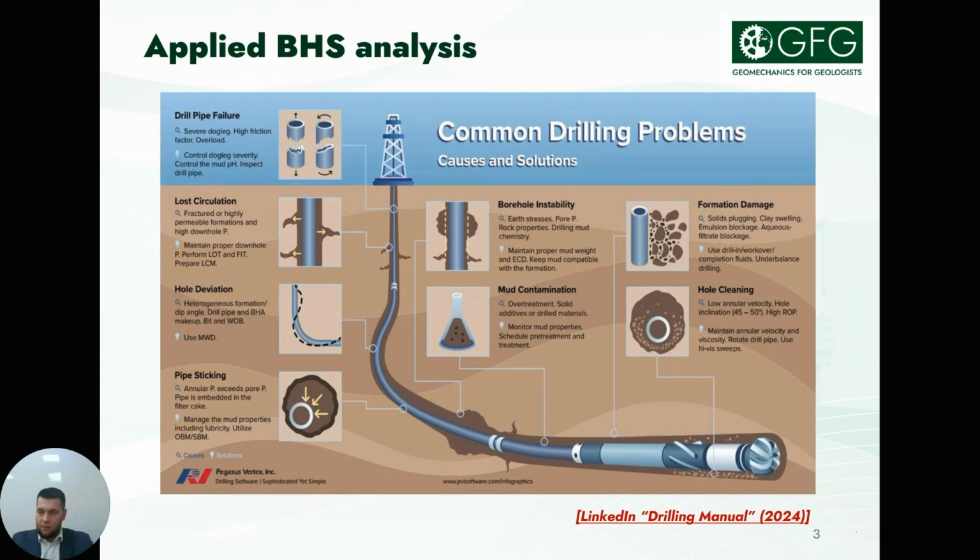Geomechanics plays the most important role at the stage of refining drilling parameters and optimization of the drilling process. At the drilling stage, geological and technological complications are possible, associated with losses of circulation, large deviation from the vertical column, instability of the borehole, damage to rocks, problems with cleaning of the borehole, etc. A correctly constructed geomechanical model allows us to reduce these risks and also reduce non-productive time and ineffective costs.